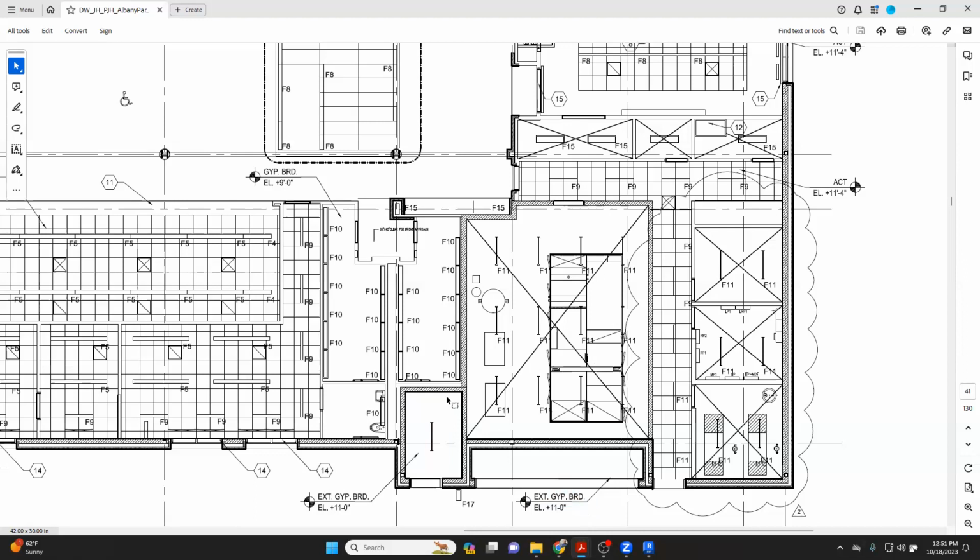But I prefer to have a chipboard ceiling with a stipple pattern, like a sand pattern, like an AutoCAD sand pattern, so I know there's a ceiling there. Because if it's white, I don't know if it's a mistake, if someone forgot to add the ceiling in those areas, or what's going on. They don't have the big X through it. This big X means there's no ceiling above here, so you leave those areas alone.